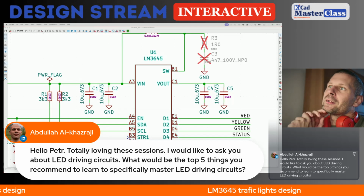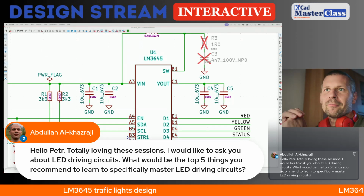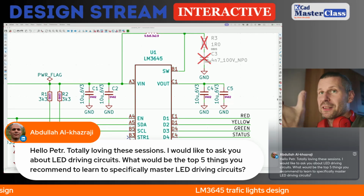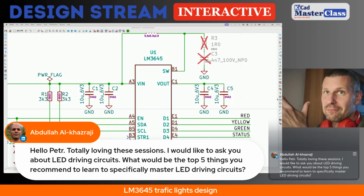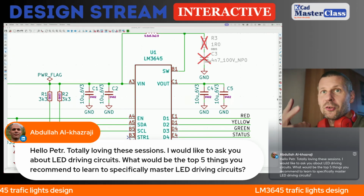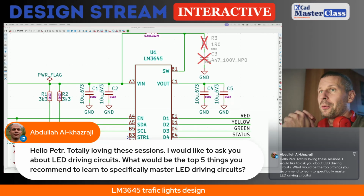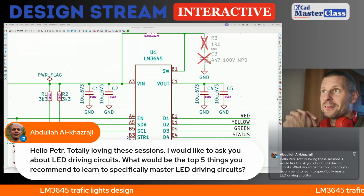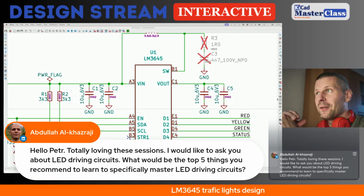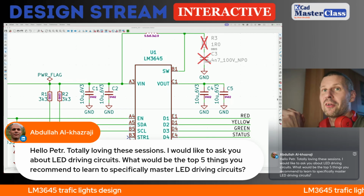You can start with LEDs. At first, an LED looks like a simple device. What can be complex with it? Two electrodes, 2 pads, 2 wires, some forward voltage drop. Nothing strange, right? No. LEDs can be tricky. You have to be careful about the reverse voltage, which is very low.